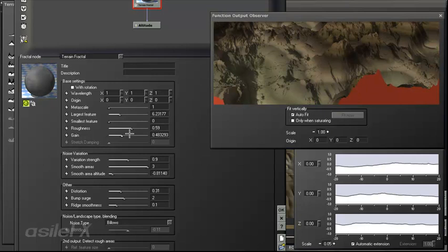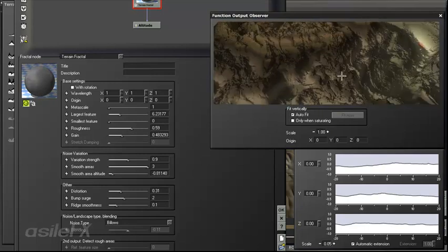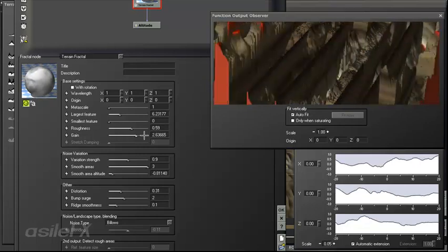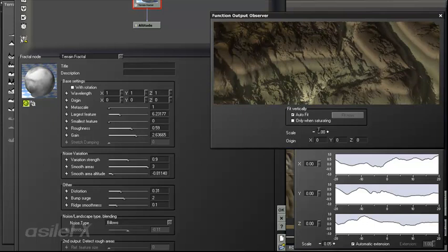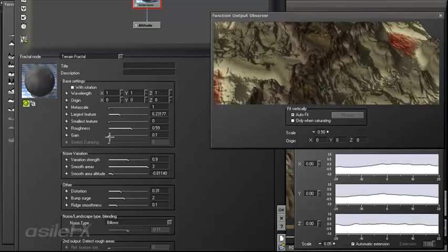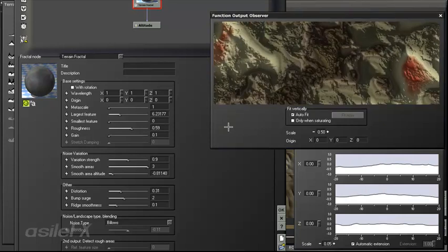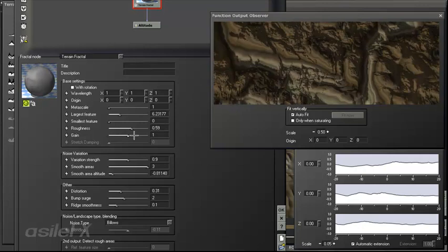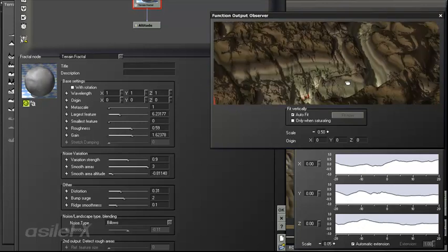The terrain fractal is a combination of several fractals together blending, and the gain itself increases or decreases the impact of the blend of those separate fractals. So you can actually go between what looks like ridges now by reducing the gain up to more of a billowy look once you get above 1.